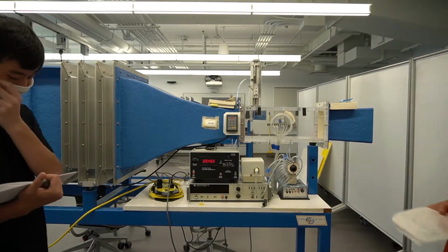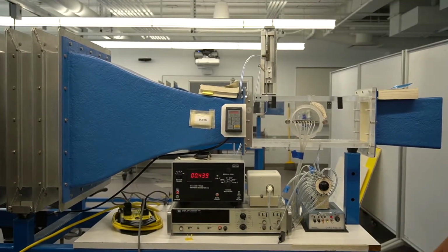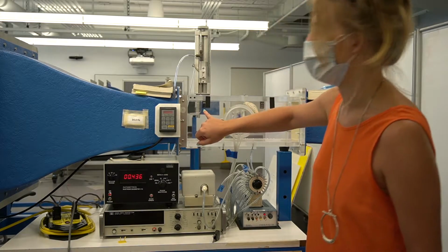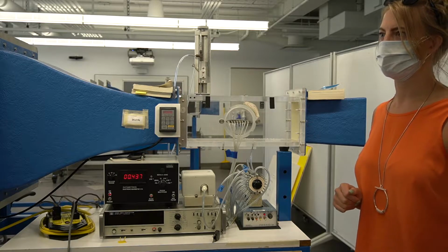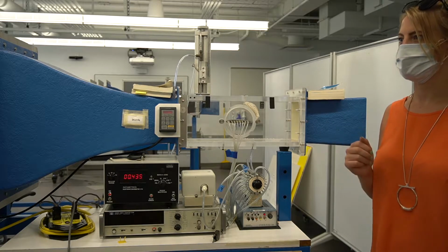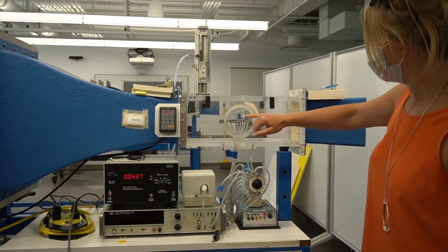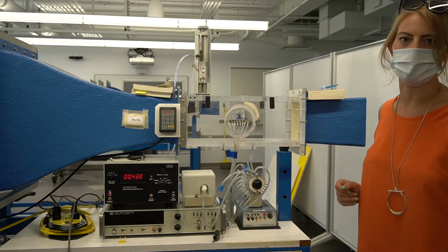So you can see the instrumentation's a little bit different to the force balance experiment. So once again, we have a pitot-static tube at the front of the wind tunnel. And what's that going to measure for us? That's going to measure the dynamic pressure. Which is equal to? PT minus PS. PT minus PS. So then we notice there's a series of pressure taps coming out of the airfoil.